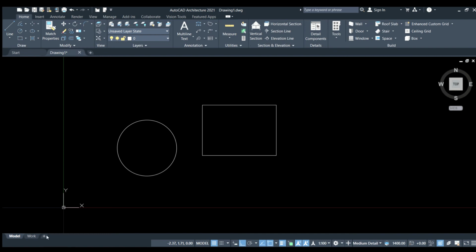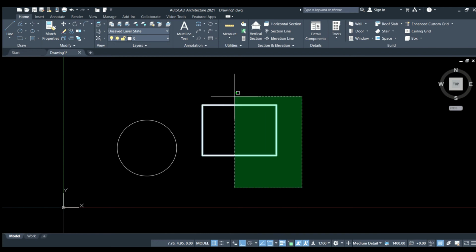So suppose we have given a line weight to that object and you don't want to see the line weight now because you are just at the drafting stage. You have assigned the line weights in the layers, but you don't need to see them. You can just turn it off. You will see a regular drawing. It will still show the color of the lines and everything, but it won't show the line weight. Get it? Great. So when you turn the line weight on, you will see the line weight of the drawing.